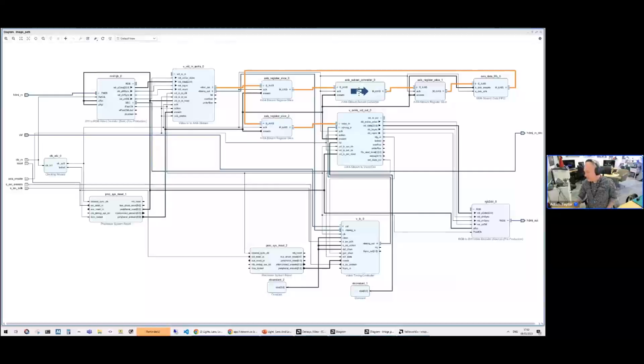Dennis, what are you using for VDMA to DDR transfer? What does that software look like on the Linux side? What VDMA do you recommend? So Dennis, we generally use the AMD drivers that come with it in PetaLinux to support that. It's actually not that difficult to set up and get running. The best way to do it is to create the Video4Linux2 pipeline, and then all of that is kind of abstracted for you, and you don't have to worry about that. I know I keep saying go look at my Hackster, but there is, I think, a project on that where we did the Video4Linux pipeline.